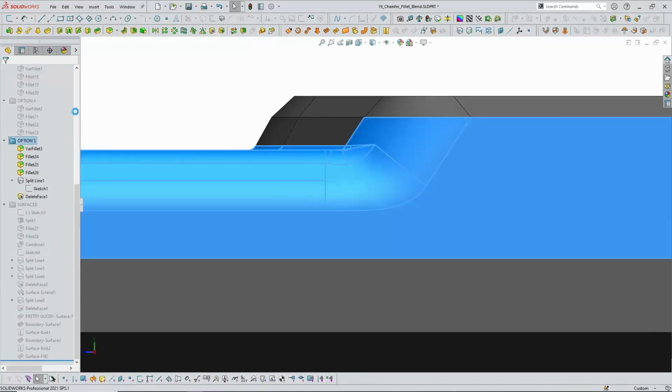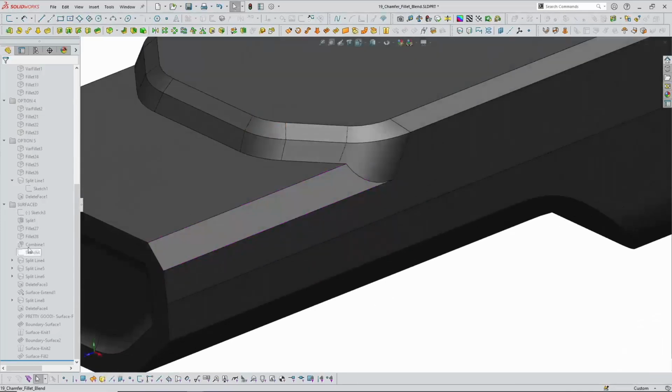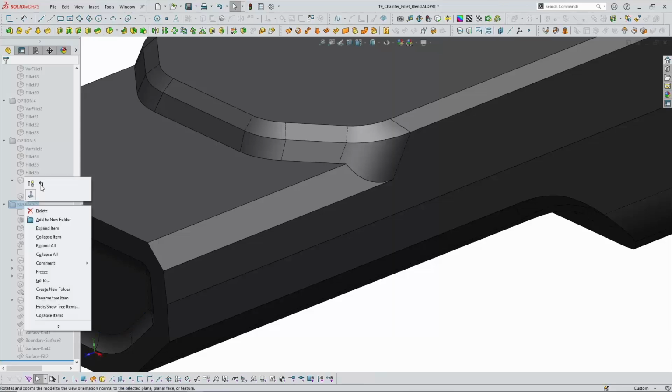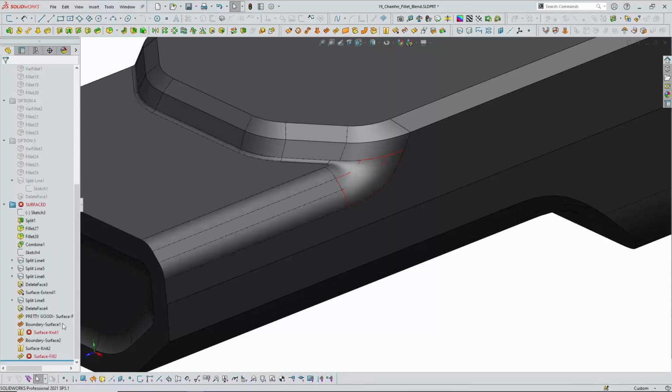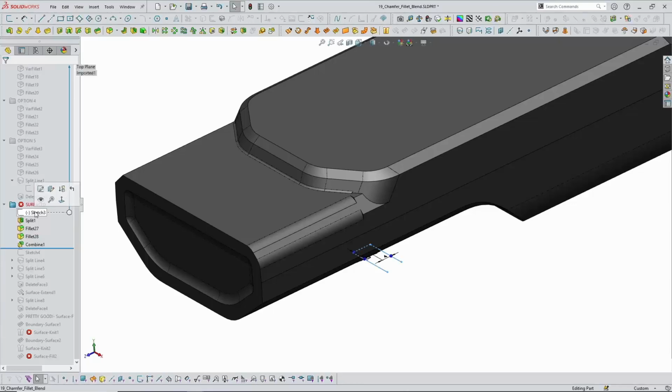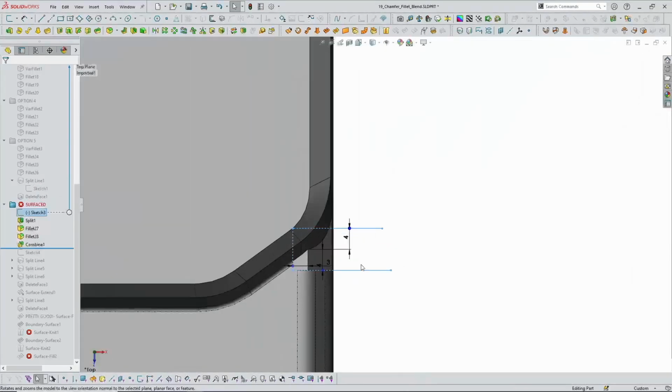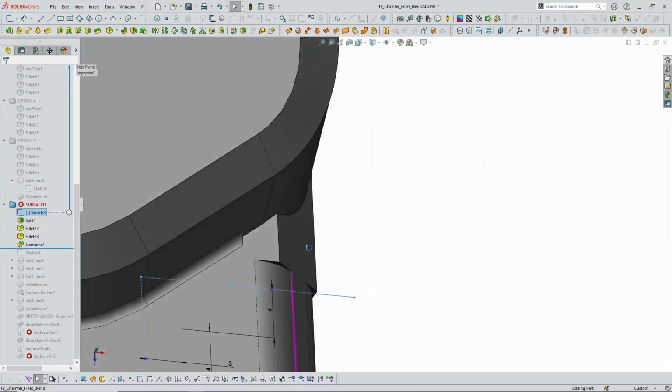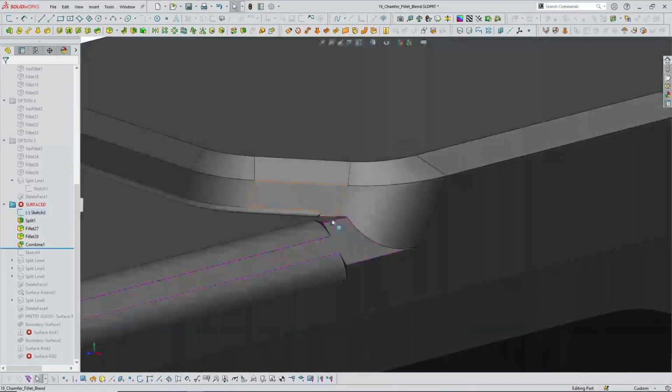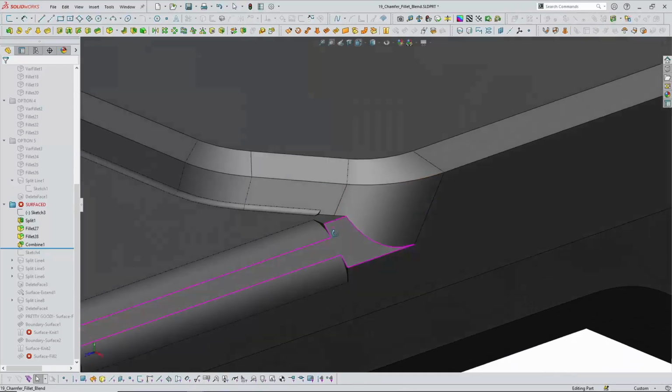And then the final option I would like to go over here is the fully manual option of employing surface features to get a couple different results, and we'll run through these. This is a situation where the split tool was great. So this was my splitting sketch. I'm using this to isolate this little corner of the model, and I got most of my fillets. I don't need to manually model these fillets with a sweep technique or whatever have you. I want to use the fillet tool, but I want to manually just control this intersection.